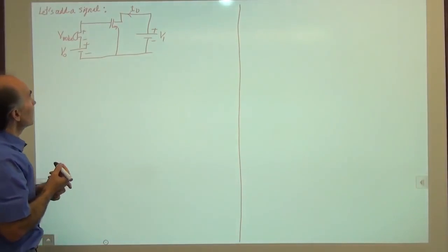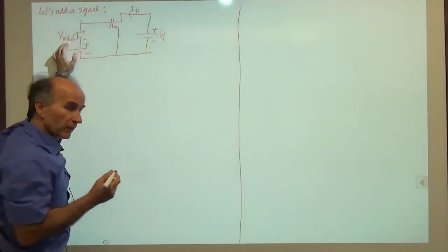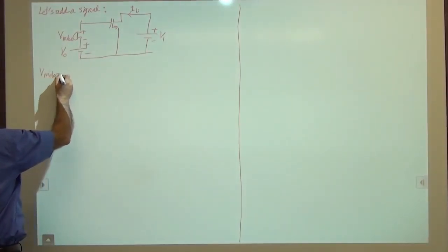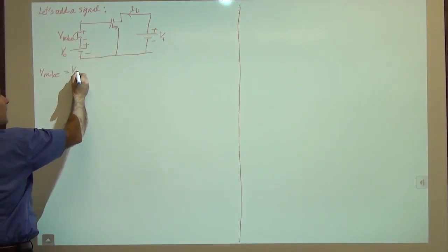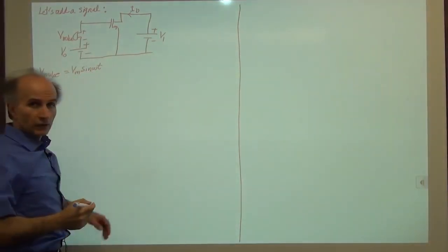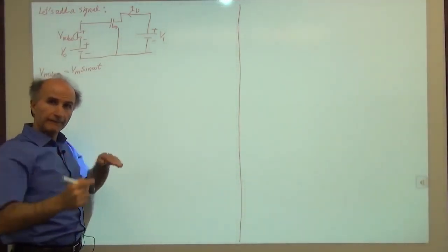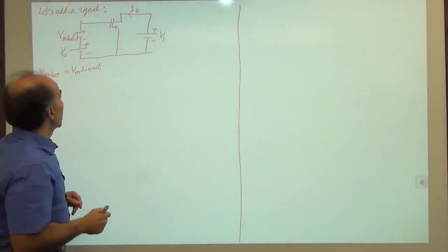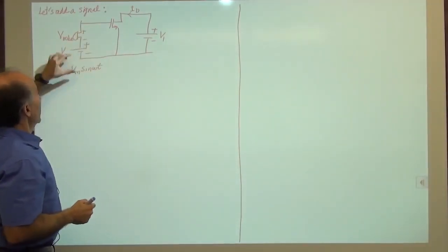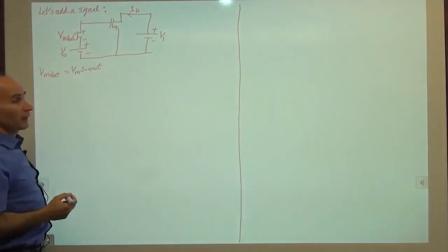Okay, so let's imagine that V mic is just a simple sinusoid. So V mic is equal to Vm sine of omega t. That's all. It's a little sinusoid with 0 DC. It just goes up and down around 0, right? But it's added to V0. So this VGS now has V0 plus this in it, right? Okay, so can I find ID?